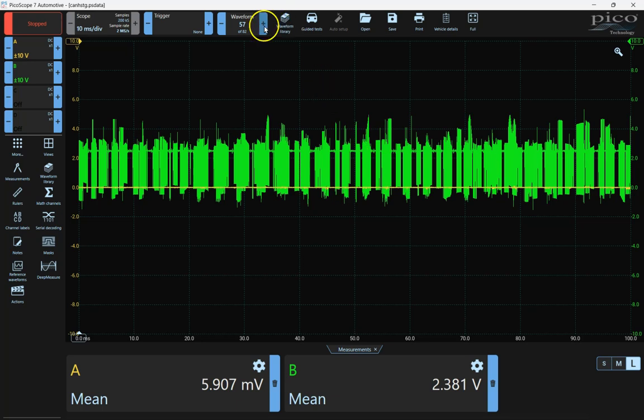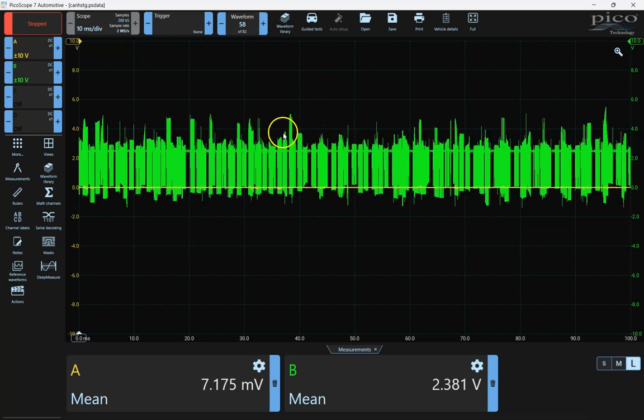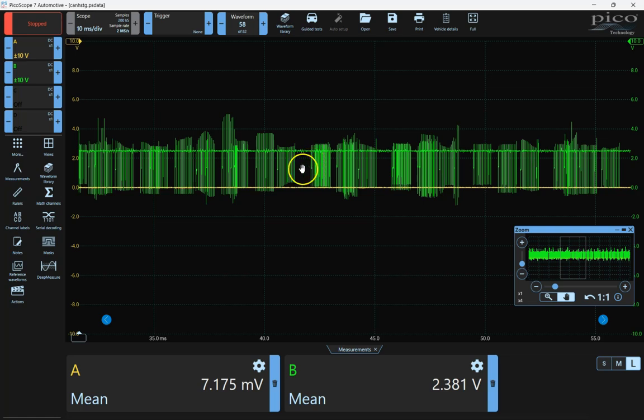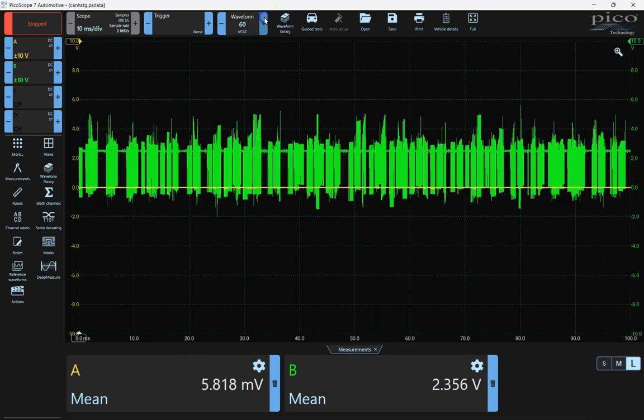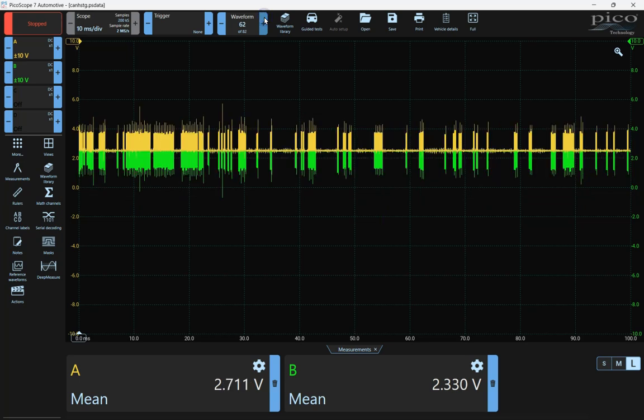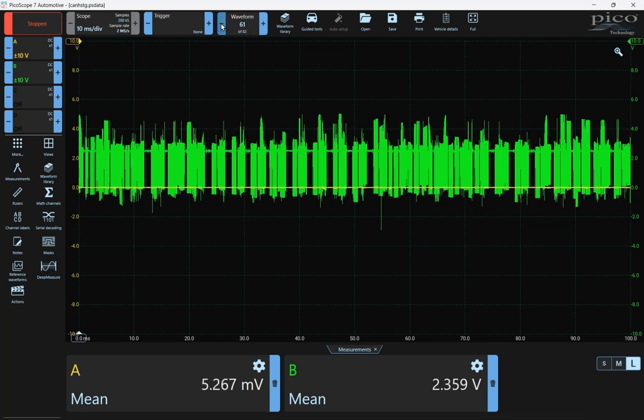This definitely looks different than the passively terminated network, but we can definitely tell by the value near 0 on CAN high that it is shorted to ground. Once again, with a multimeter it's not hard if this is in place, but if it is intermittent and very brief, it may be tough to catch with the multimeter.